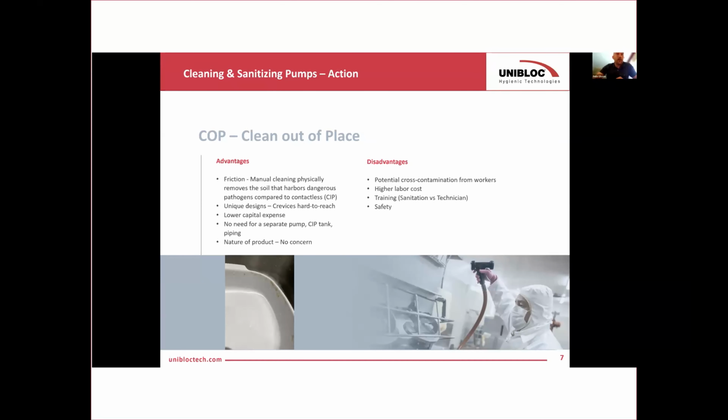So the other advantage would be that the capital expense, the initial cost, is less. You don't need the additional piping, tanks, etc., and pumps. And the nature of product, that was a concern in the CIP. You don't have to be worried about that here, since you will manually see it and you can manually add that friction method to clean out the equipment.